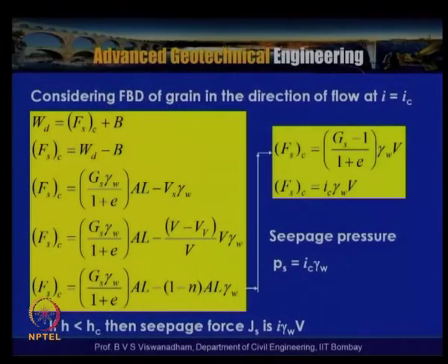And considering the free body diagram of the grain in the direction of the flow at i is equal to ic, if you simplify this, we will be able to calculate the seepage force acting in a given volume where the flow is occurring. If you take the seepage force per unit volume, you will get the seepage pressure. The seepage pressure, which is nothing but the seepage force per unit volume, has units of kilonewton per meter cube.